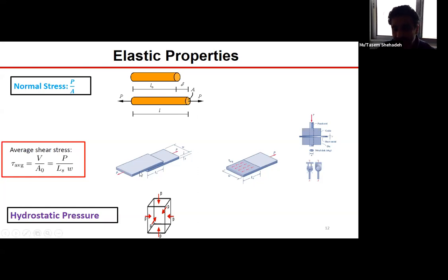In the second picture, what you see is two bonded blocks that are subjected to an axial force F. When this sample fails, it will fail by delamination or by sliding. So in this case, the gluing material undergoes a shearing behavior that leads to its fracture. And one can also define here an average shear stress and an average shear strain for this